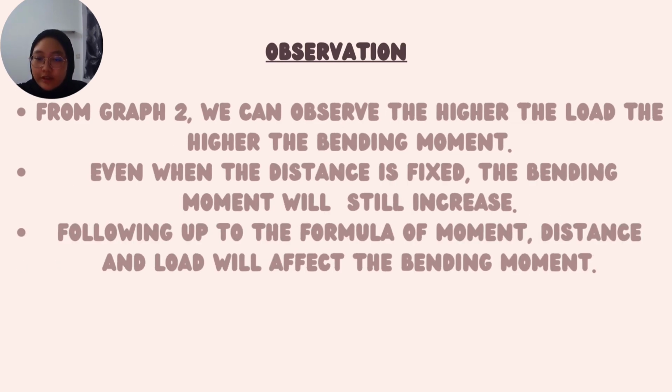From graph 2, we can observe that the higher the load, the higher the bending moment. Even when the distance is fixed, the bending moment will still increase. This is due to the formula of moment, which is force times distance, where distance and load both affect the bending moment.